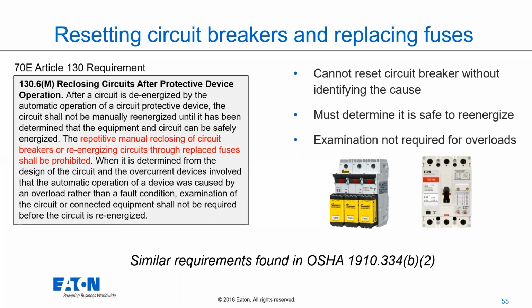When that occurs, it most likely means you have a short somewhere on your system. You really don't want to close an overcurrent protected device into a fault. They are not made to withstand something like that. They're supposed to be in a closed circuit, see a fault and open. They're not supposed to be closed into a circuit with a fault.